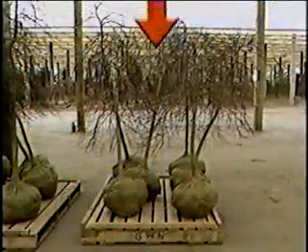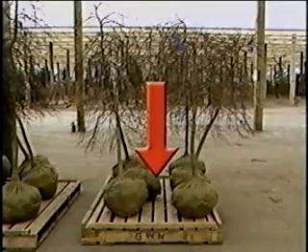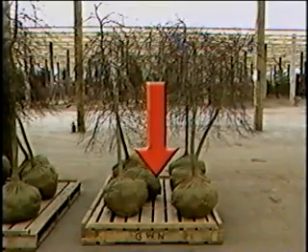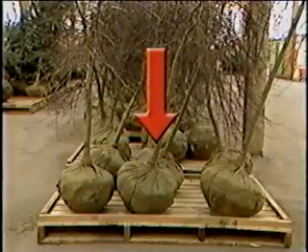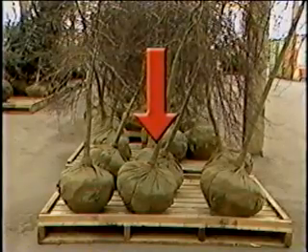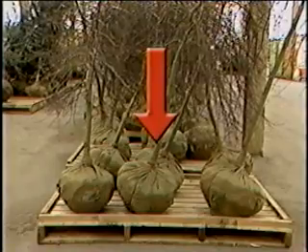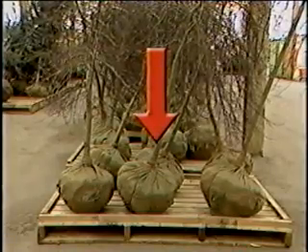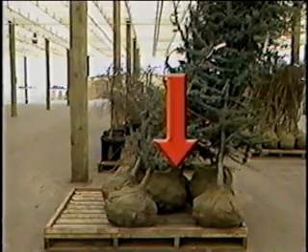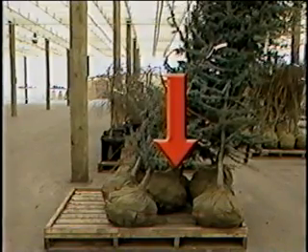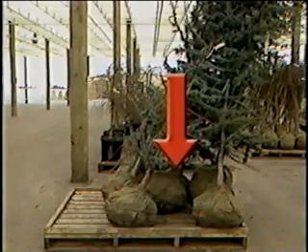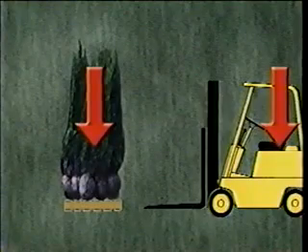First, we'll start with the center of gravity of the load itself. In the case of this pallet of trees, the center of gravity is pretty much the center of the pallet because the load is evenly distributed over the entire surface. When judging the center of gravity of an odd-shaped load, it is generally at the center of the bulk of the weight. In this side view,